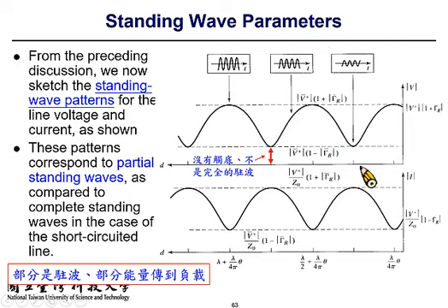On the other hand, if you have short termination or open termination, which means that all the incident power is reflected back, then you will form some voltage maximum, and the voltage minimum is what? It is 0. Now it touches the ground. So the division of some value over 0 is what? It is infinity. So you have some extreme cases.